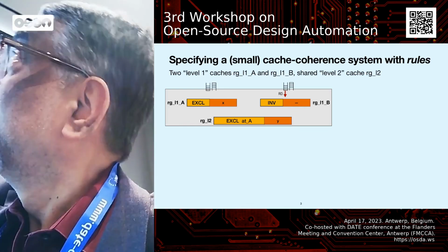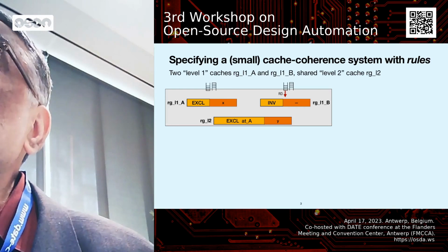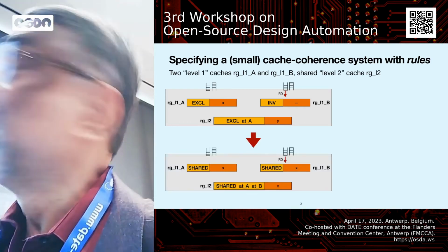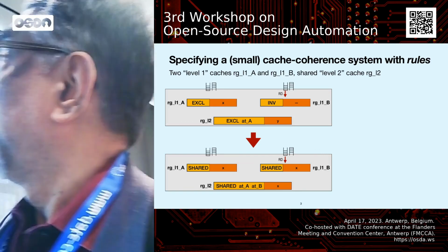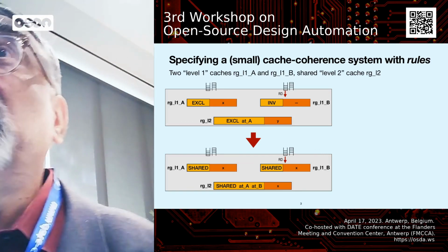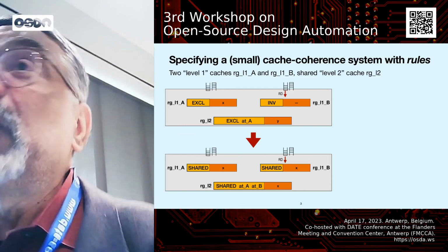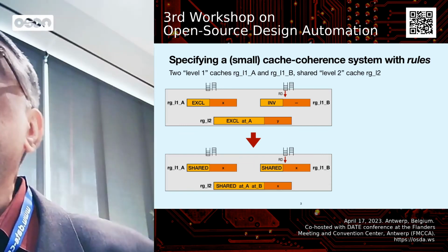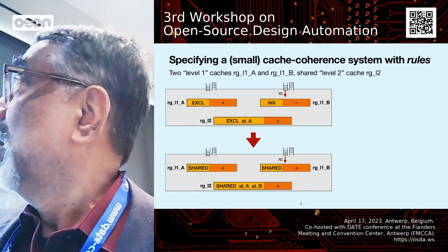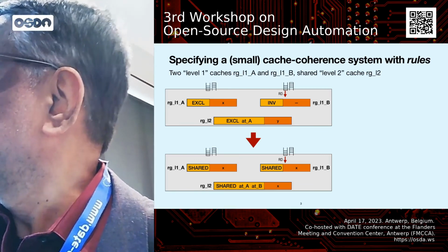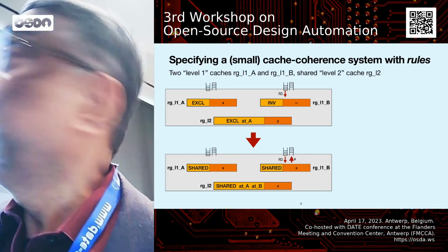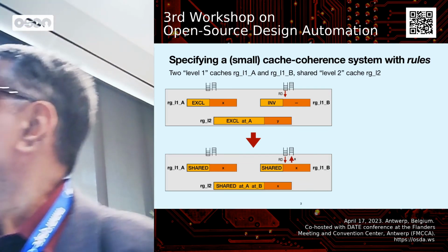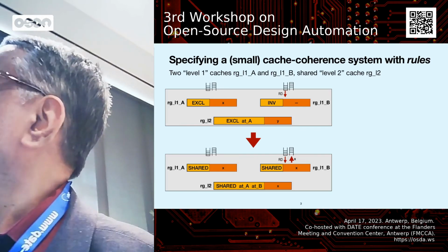And now imagine a read request comes in to B. So we can imagine transitioning to a state like this, where the states have all become shared. The current value X is available everywhere, and L2 has a notation that it's available at both A and B. Once we have it in the state, seeing a read on B, we can immediately satisfy the read and put back an X.